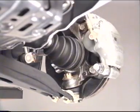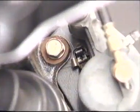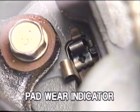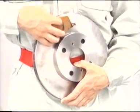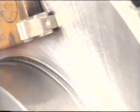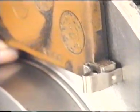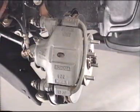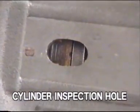In the front disc brakes, a pad wear indicator is provided to alert the driver that the pad needs to be replaced. When the pad wears out, the pad wear indicator makes contact with the rotor disc and makes a screeching noise during driving. Check the pad thickness through the cylinder inspection hole and replace pads if not within specification.